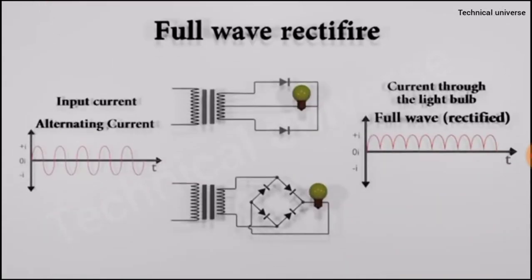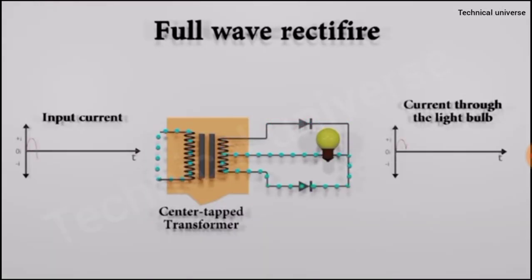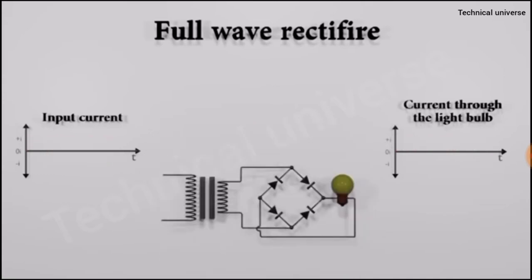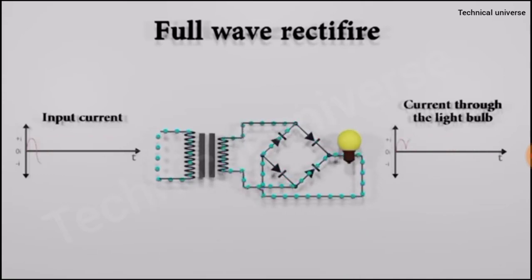There are two major types of full-wave rectifier designs used frequently. A full-wave rectifier converts both the positive and negative halves of the input waveform to a single polarity, positive or negative, at its output. By using both halves of the AC waveform, full-wave rectification is more efficient than half-wave. When a simple transformer without a center-tapped secondary is used, 4 diodes are required, instead of the one needed for half-wave rectification. It is called a bridge rectifier. This 4-diode configuration is called a diode bridge circuit.